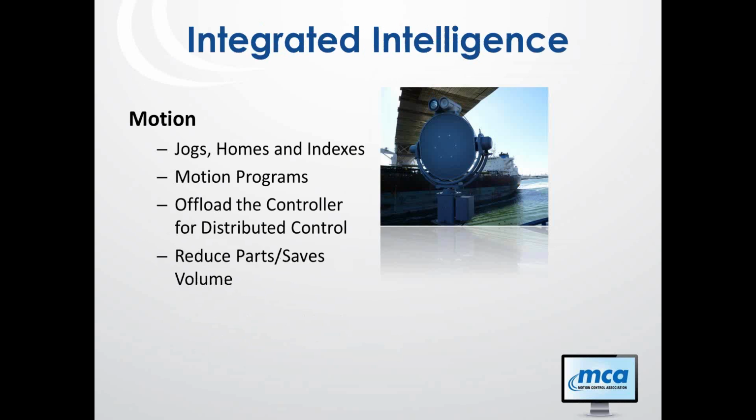And the last piece we want to talk about is how do you make your system more efficient from a processing standpoint? Well, the servo drives have a lot of built-in capability already in them. So if you can offload some of the processing needed at the control level and push that down to the drives, you can pick a lower end processor and more thermally efficient processor for the controller. You distribute all the motion control down to the drives, whether that's jogs, indexes or homes, or even having sequences or programs inside the drive itself. And that really just allows you to make your part count more efficient from an energy standpoint, and it just saves in the volume overall of your system.